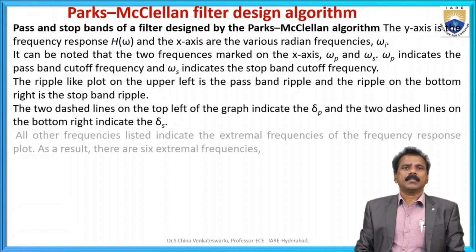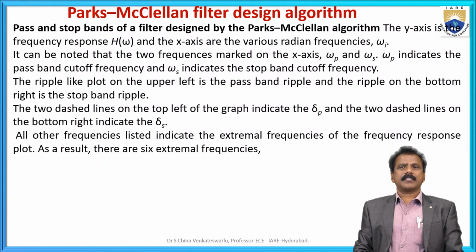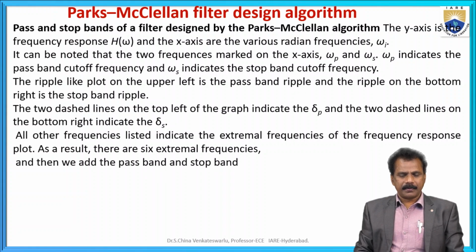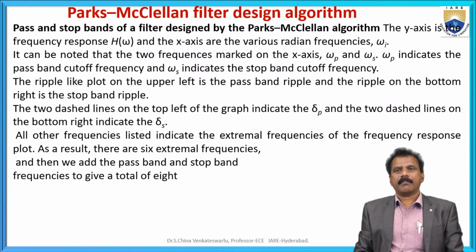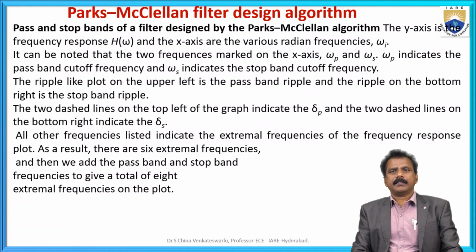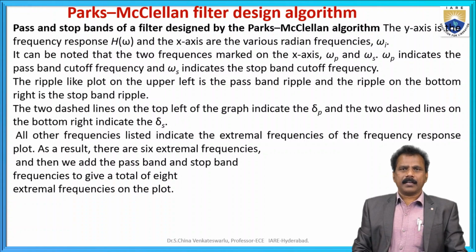All other frequencies listed indicate the extremal frequencies of the frequency response plot. As a result, there are 6 extremal frequencies as per the graph. Then we add the passband and stop band frequencies to give a total of 8 extremal frequencies on the plot. We have just verified this graphically.